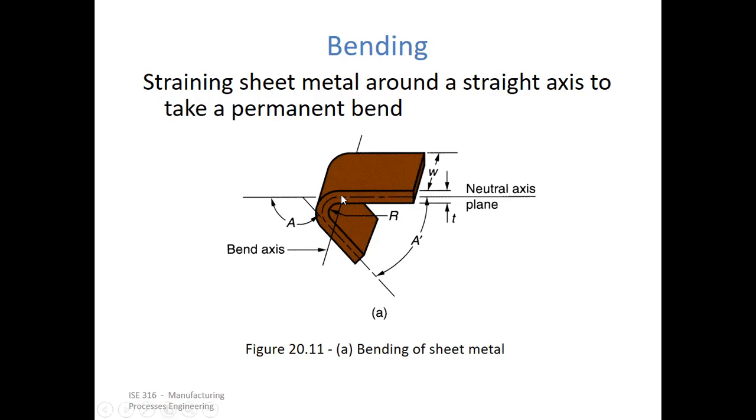You have a plane or an axis that goes in between the total thickness that is not affected by either tension or compression, right? The outermost profile here you can see would be experiencing tension when that bend is executed or performed, right, using a bending machine. And the innermost layer would experience compression, right? Especially here, more of a compression here than it is at some other points.